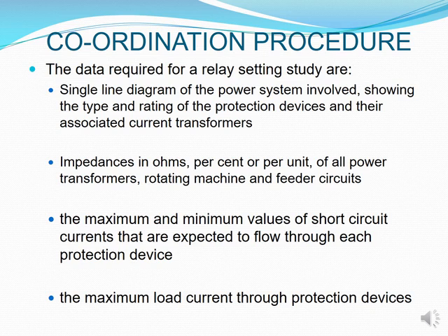Then the second one is you need to know your impedances in ohms. In other words, that distance gets translated into your impedance. Now, all of your wires or your conductors and your cables usually have impedance that they are provided with by the manufacturers. And all you need to do is to multiply that by your distance from a certain point A to a certain point B. You also need to know the impedances of all of your transformers or your rotating machines and feeder circuits.